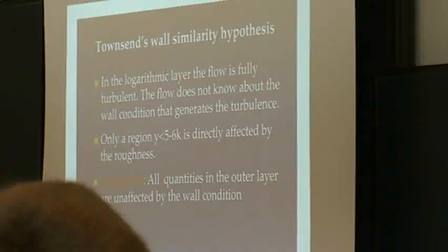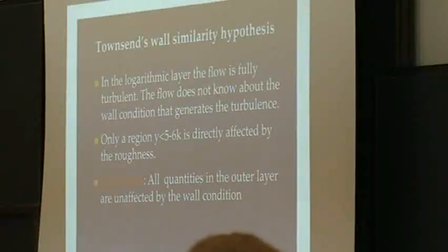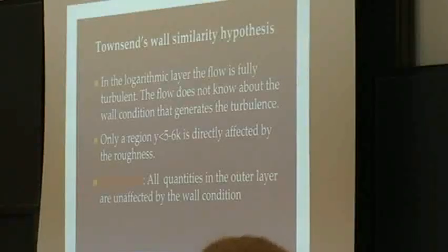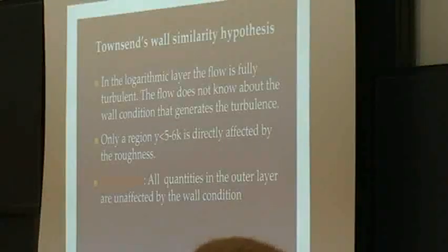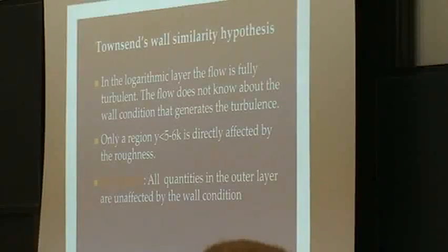surface roughness. And you can easily imagine that it needs to be like that if you look at the perturbation around a cylinder that you insert into a flow. Then you will see that if you move away some 4 or 5 diameters, then the perturbation has dropped down to 1 or 2%.